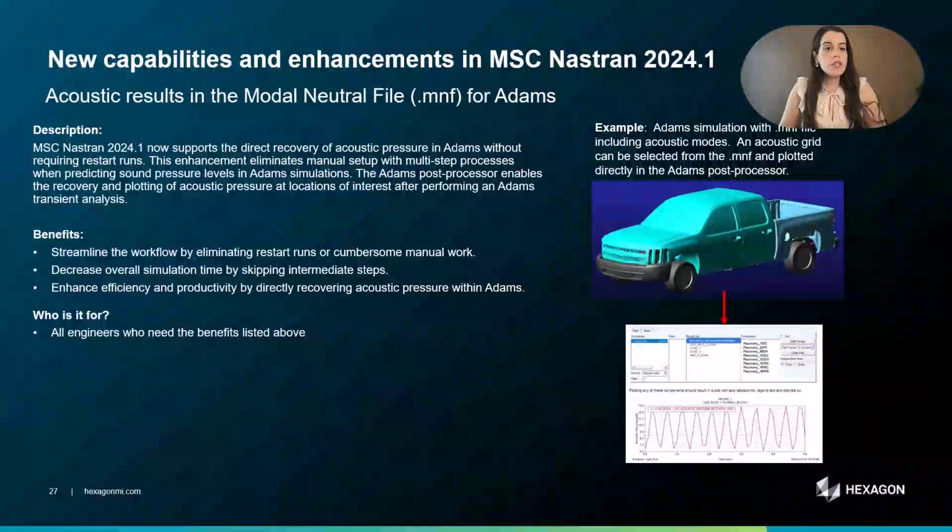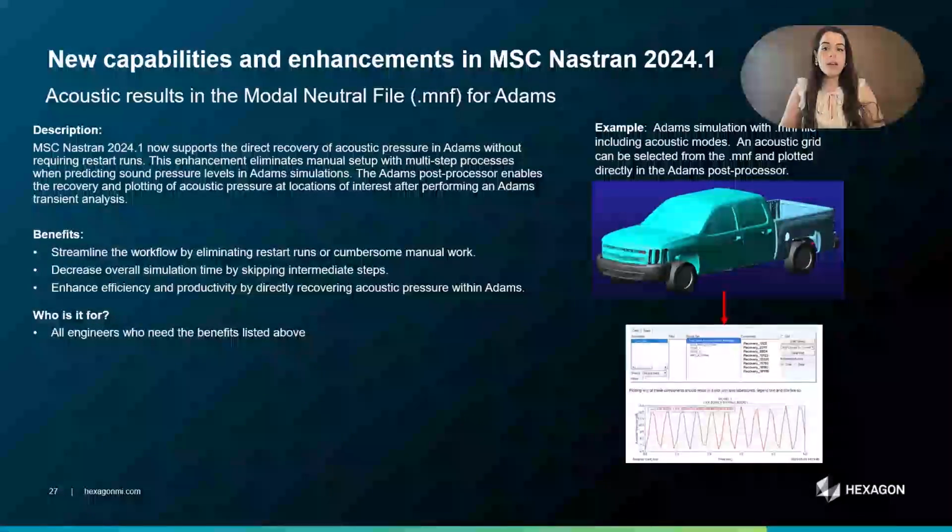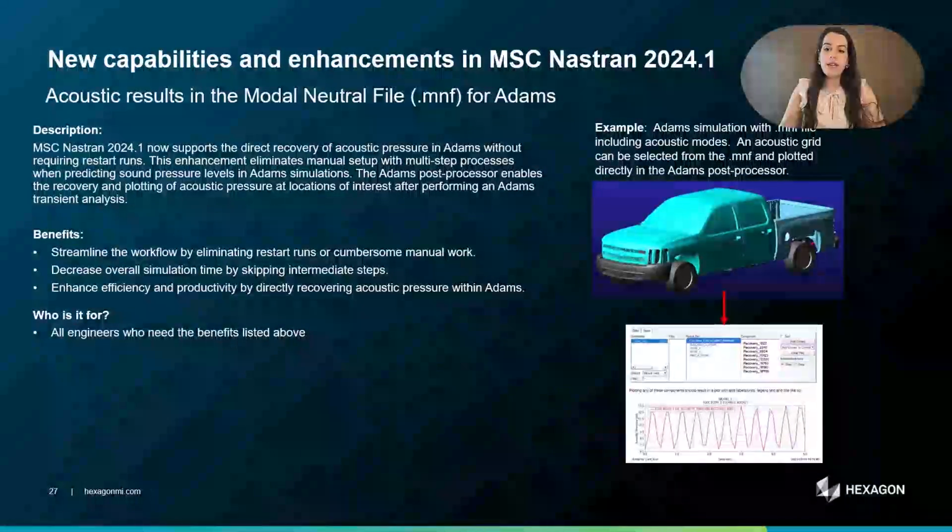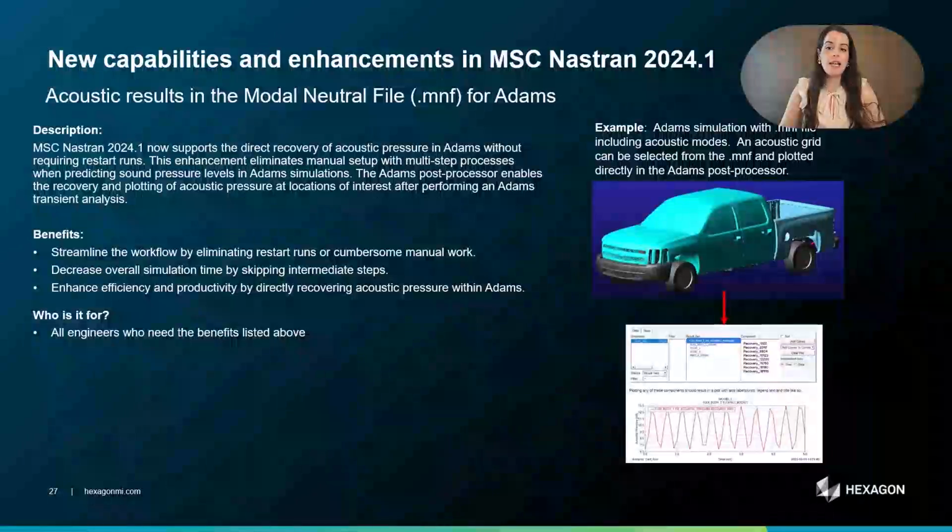In MSC Nastran version 2024.1, we now support the direct recovery of acoustic pressure in Adams without requiring restart runs. The acoustic results are now embedded in the modal neutral file, abbreviated MNF file, utilized by Adams. This enhancement simplifies the prediction of sound pressure levels in Adams simulations by eliminating manual setup and multi-step processes.